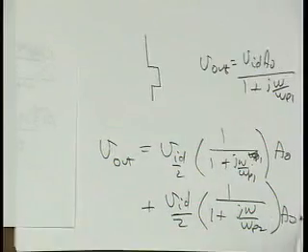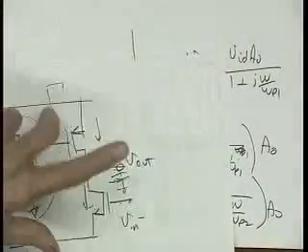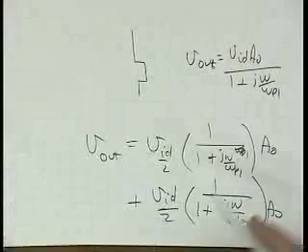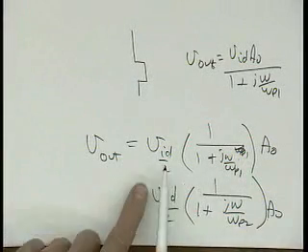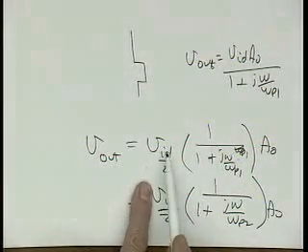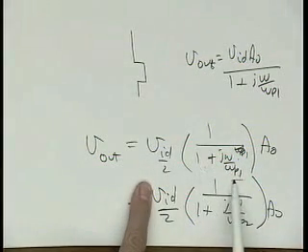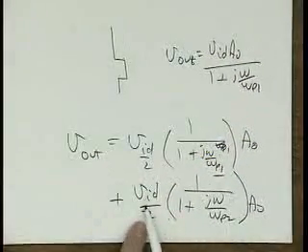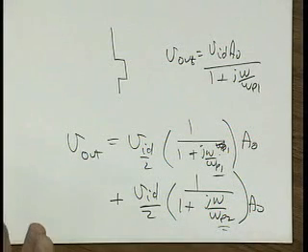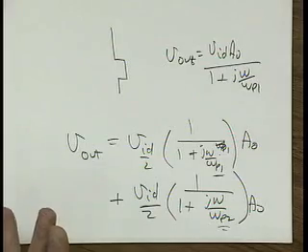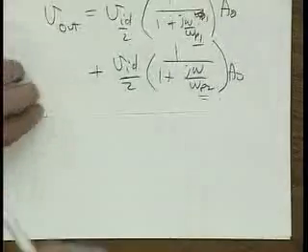But now let's say because of this mismatch we have two different poles that are slightly different from each other. So our transfer function to the output from one side is associated with pole 1, and from the other side is associated with pole 2. Okay? See what I'm doing there? Now, let's take